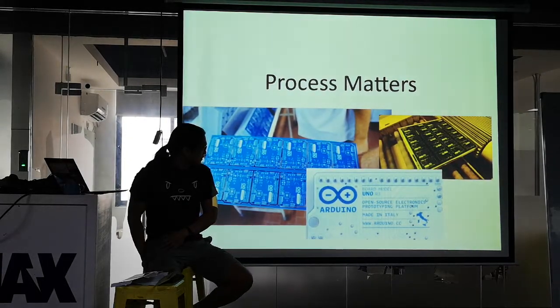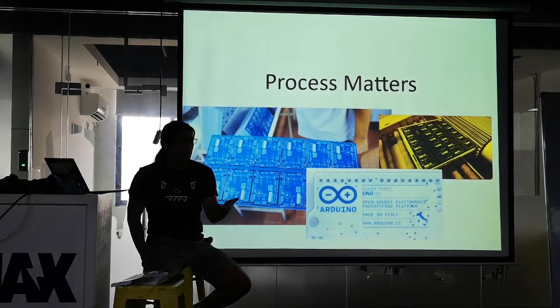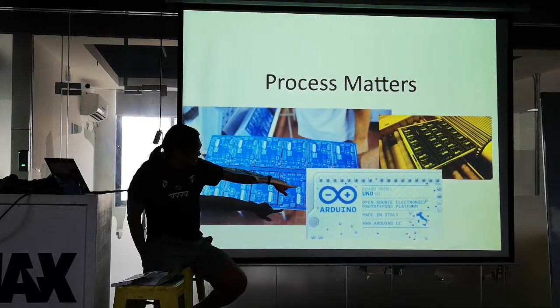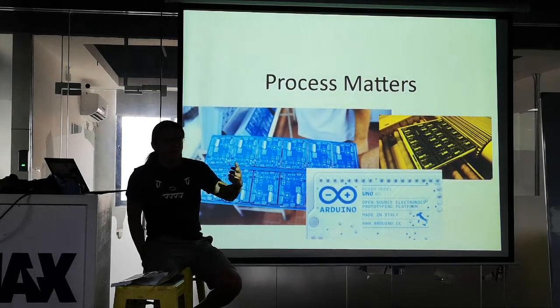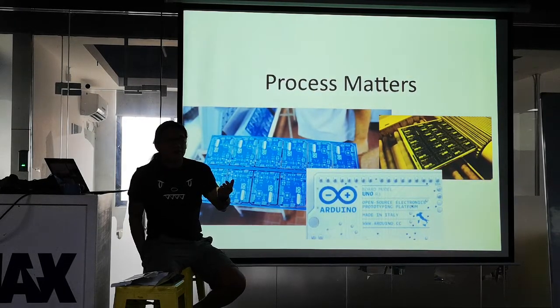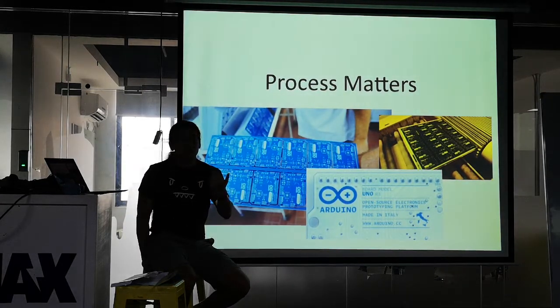So when you go to the factory, and this is the reason why we visit all of them, you can learn little tricks like this that can greatly improve your product quality without having to pay a lot of money. If you're trying to get that quality with a silk screen, you would hammer on the factory, like, oh, we reject this. The silk screen mesh isn't fine enough to do it anyways. You're at the limit of the process. You have such a high scrap rate and such a dumb process step with silk screen, right? But if you swap it for two solder masks, then your yield goes up and your cost goes down.